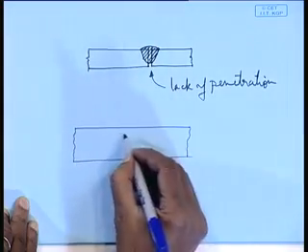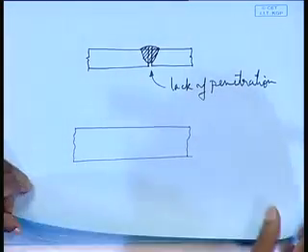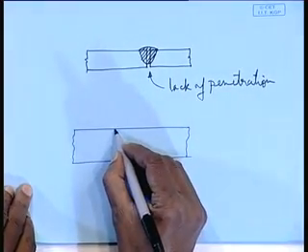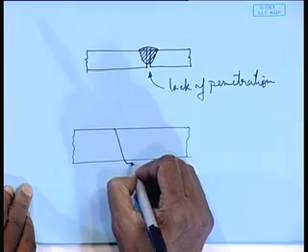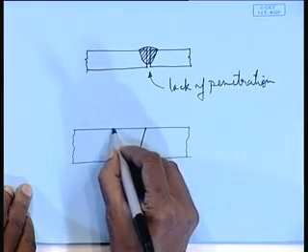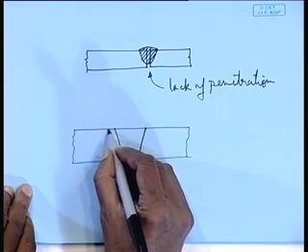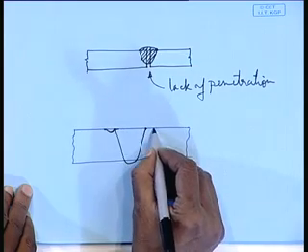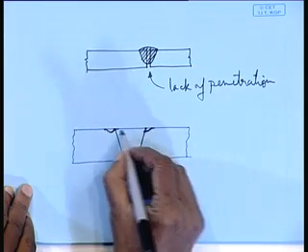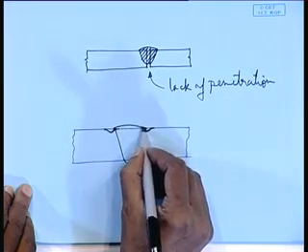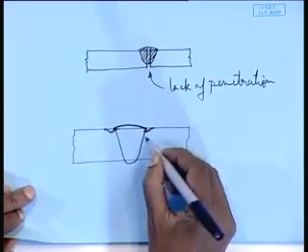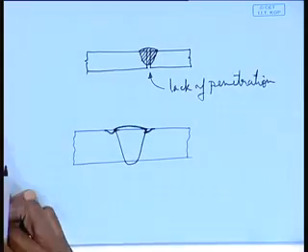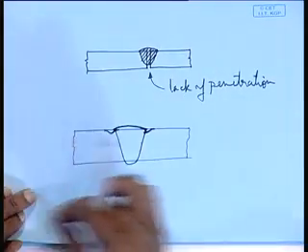It is a case, what happens is, when welding is done, if the welding speed is too high, then at the edges of the weld bed, the weld reinforcement forms like this, and at the edges, a small narrow channel-like thing forms.